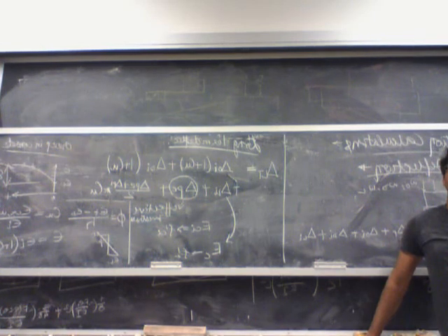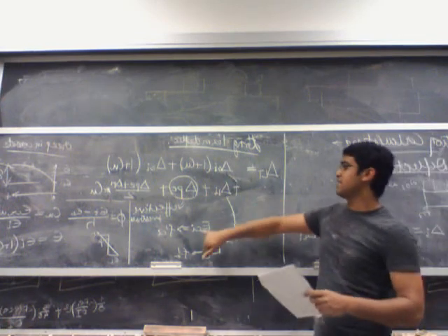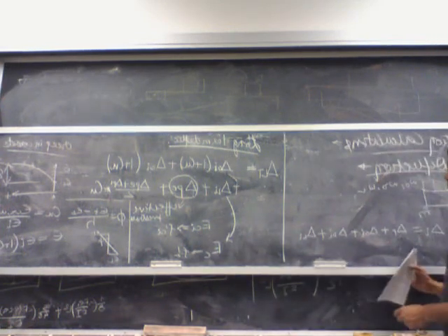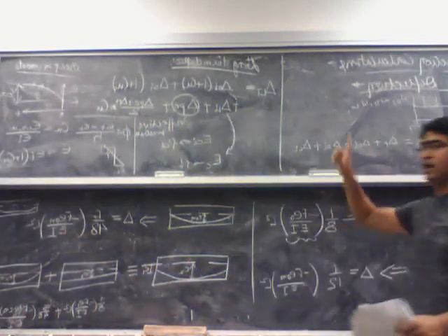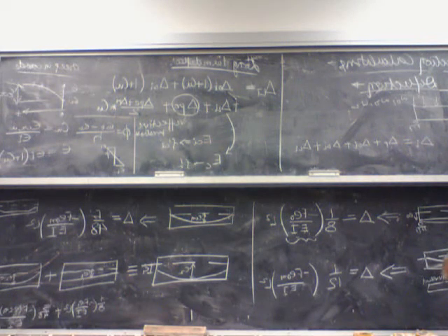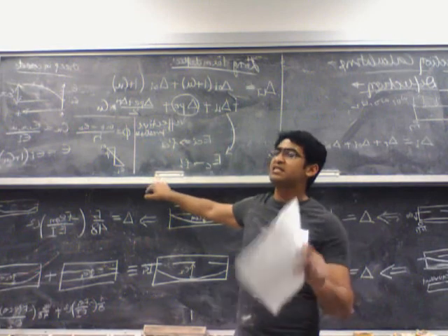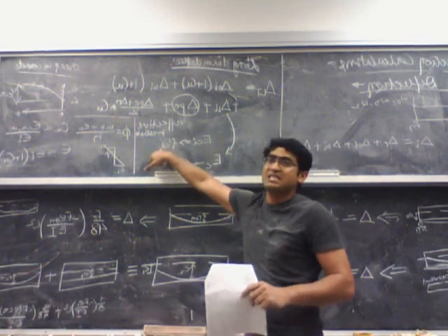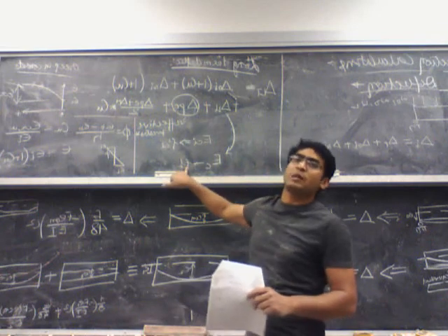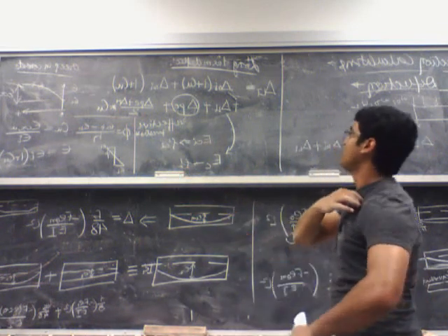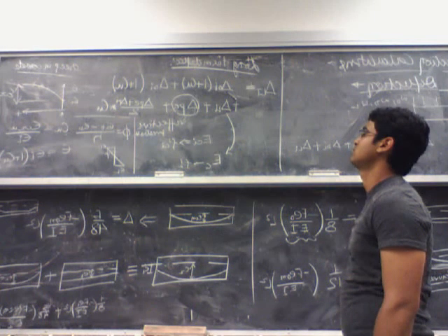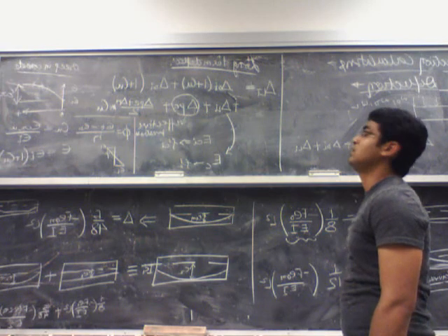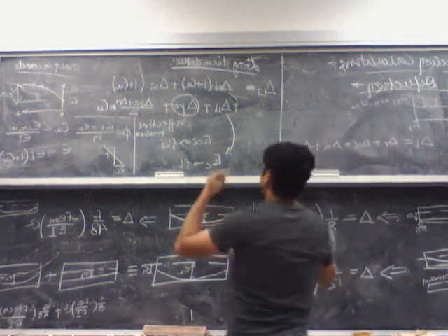Okay. So because Ec is used in finding out this phi, right? Right here. EI, even for the loads you have moment at the midspan divided by EI. So for all the other terms you will use the initial Eci, which is based on f prime ci, but for the live load you always use f prime c. For the dead, let's see. Actually, yeah, for dead also you'll use the Ec.